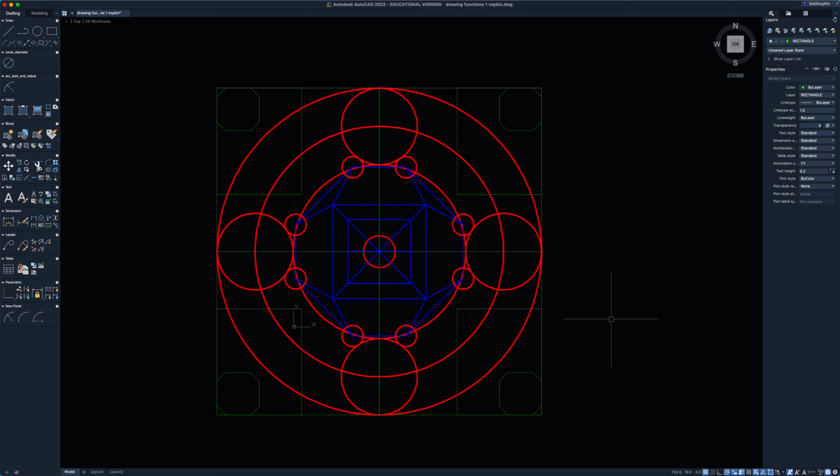So the next set of instructions, what does it say? Well, now create a square in the center of the last two bottom squares that we just made. So we want to do it in the center of these two squares right here using a side length of 50 and filleted corners with a radius of 10.